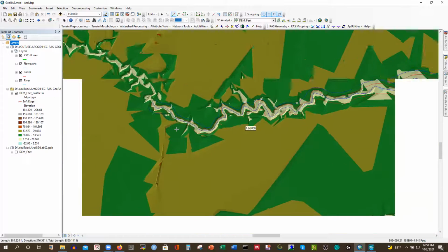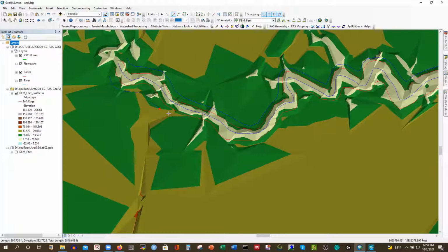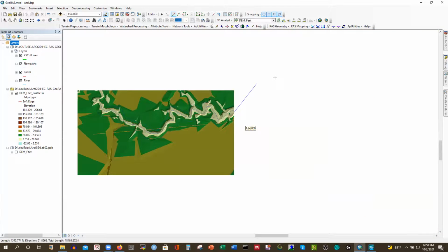So you have to be very careful and zoom in each time so that you can even follow the line and make an offset. Just maintain this distance so that it can't touch, and you can even change the snapping distance, the pixel. That is also possible. You can go to snap tool and then you can change that, then it won't touch. So it is just checking the distance between these two lines, and then it's automatically selecting the nearest point.